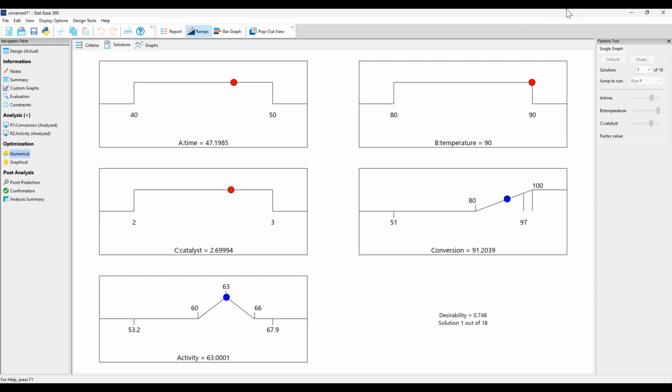Okay, so a response surface to find the optimal conditions. We had two different responses in this case, and we created models for both of them, and then simultaneously solved for the best solution that achieves the goals that we set for each of those. Now, there are a lot of other bells and whistles in this optimization module, and in a fuller course rather than a 1 hour intro, we would showcase quite a bit of the tools involved with the optimization.